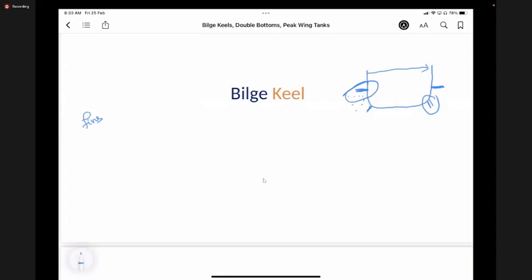So, am I clear? The upper one is a fin. No, I was just talking about a hypothetical scenario as to why can't we add like this. We don't add anything like this. This is just for the sake of asking a question. I showed you something like that. Things are all added in the same location as the bilge keel, but they have more controls. They have hydraulic systems inside the ship. They can extend a little longer, you can change this and more. They're more flexible.